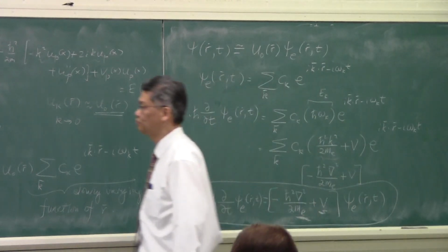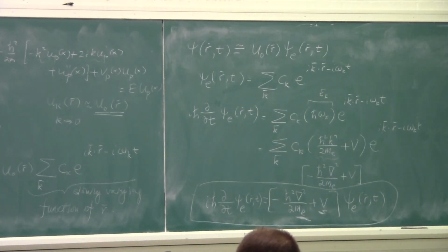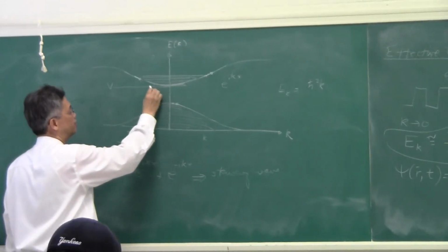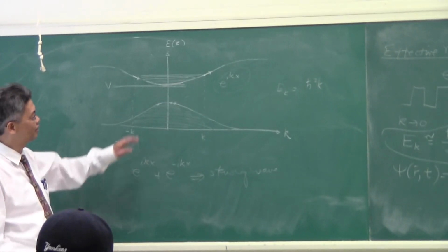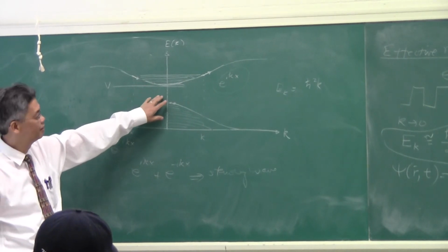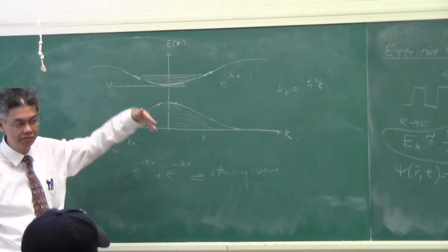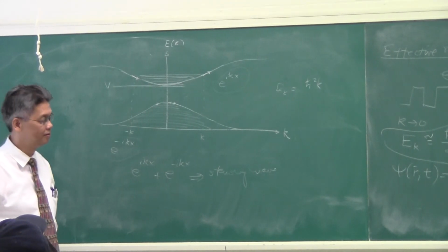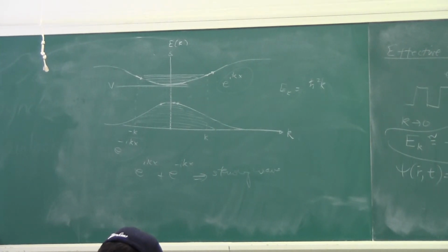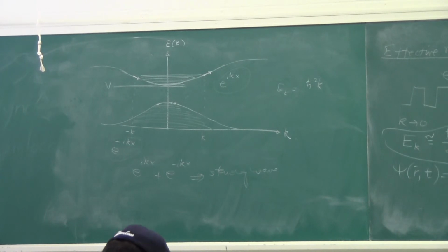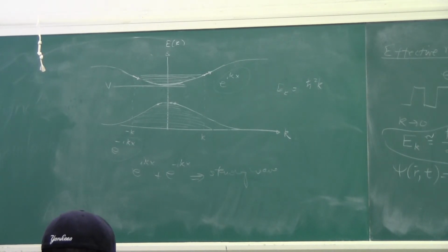Okay? How does the effective mass come about? It comes from curve fitting. You fit your curve so that this parabola has been fitted by this parabola. You pick the V so that it is the bottommost level of your band diagram. So after you have done the band structure calculation, you can take the value of V and the curve to be the mass. Okay? And that is called the effective mass Schrodinger wave equation. Okay? So effective mass Schrodinger, EMS. Okay? Are there any questions regarding this?